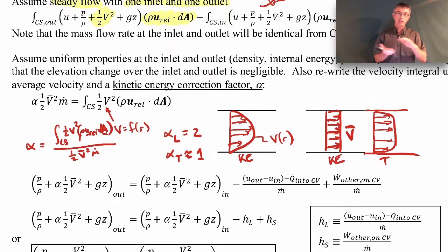So because of these viscous effects, you can imagine that, as we shear the material and we have viscosity, some of that work we put into it, some of that macroscopic kinetic energy or macroscopic work that we put into it goes into increasing the internal energy of the fluid, increasing the U here. So you get some increase in the internal energy when it goes out. The internal energy is larger going out than it is coming in. So this term will be positive in general.